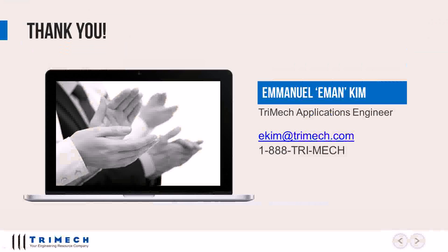Okay. Another question I'm getting asked is, can I import or use the SOLIDWORKS explode animation in Composer? Not necessarily the animation, but the exploded view that you create within SOLIDWORKS will show up in Composer, and then you can use that view technique to drag the views down into the toolbar to create that animation. So you just drag the view with the items exploded, and then you drag a view with everything put together, and it'll create all the steps in between for you. Okay, another excellent question.